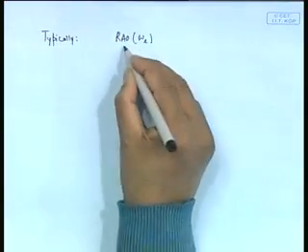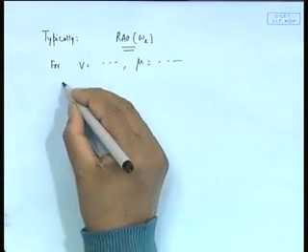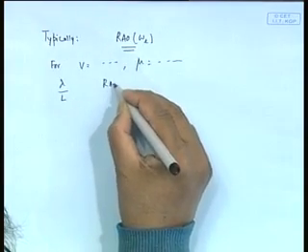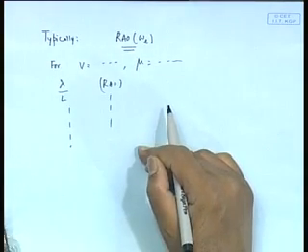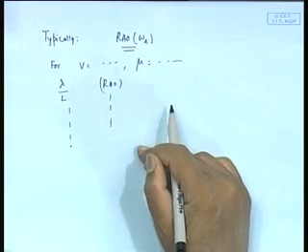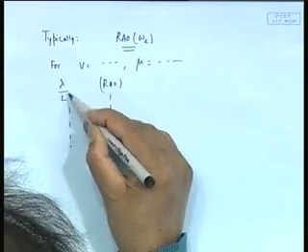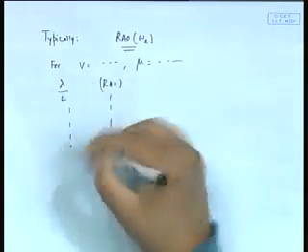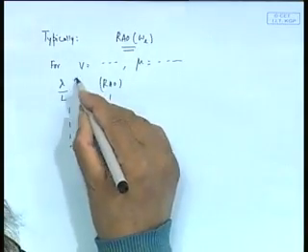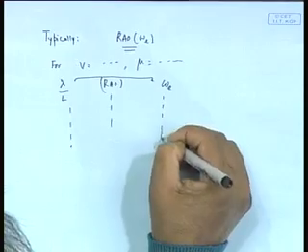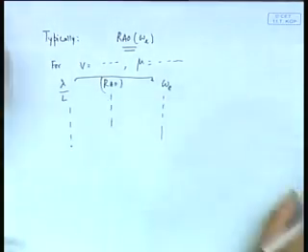For example, somebody may say that for V equal to so and so, mu equal to so and so, here is lambda by L versus RAO. In fact, many people like to write in this form. What you have to first do therefore is transform that to omega E. You can of course do that, because you can get lambda to omega, and then from omega, for this V and mu, omega E. So, you have to first transform this to omega E, and you will end up getting omega E versus RAO.